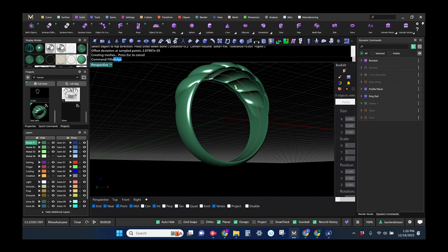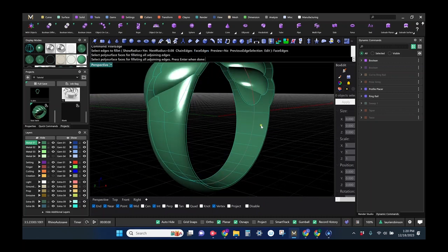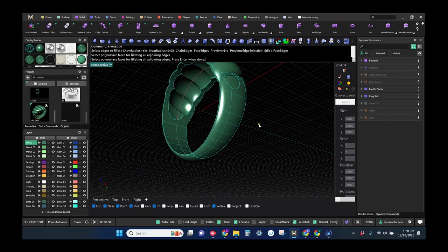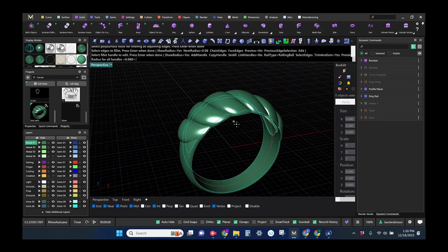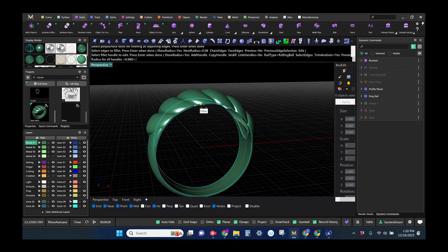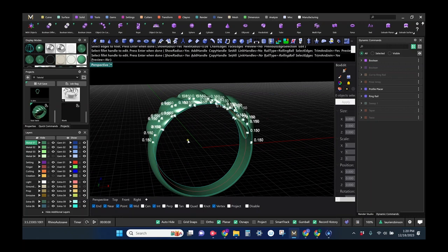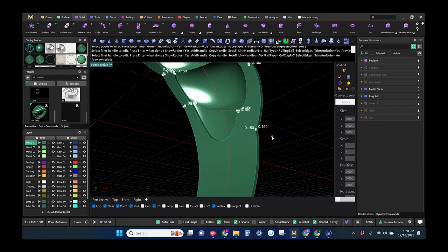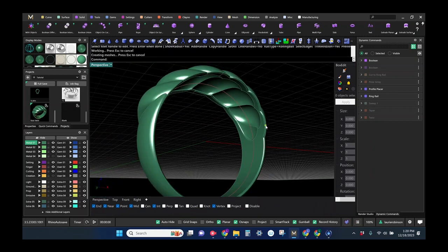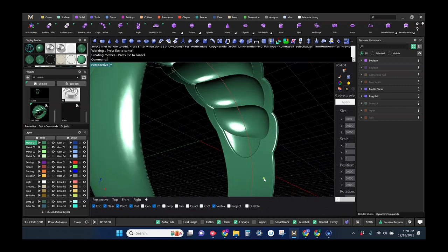And then I'm quickly going to say fillet edge. I'm going to use face edges and select this inside face. I'm going to set it to something less than 2. This is a trial and error process. Sometimes the fillets don't work exactly as you imagine, but let's try this. Okay, well, that worked.